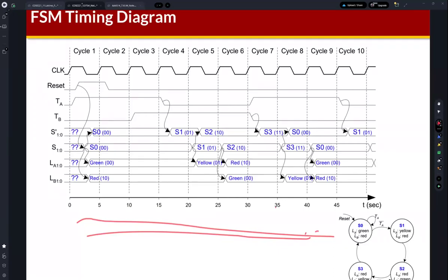In programming, the output values are immediately changed by input values. But in real hardware, like this sequential logic, some values are updated on the rising edge of clock, like the current state. So we need to understand this timing diagram.